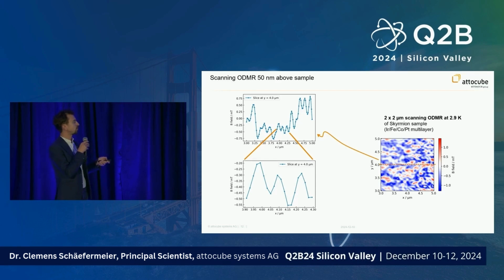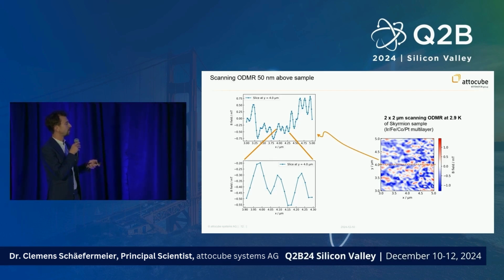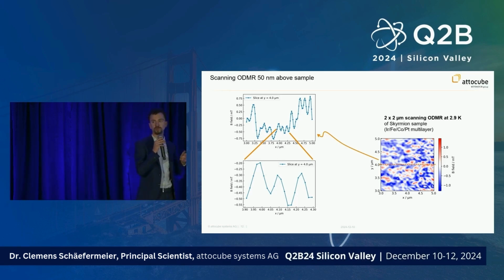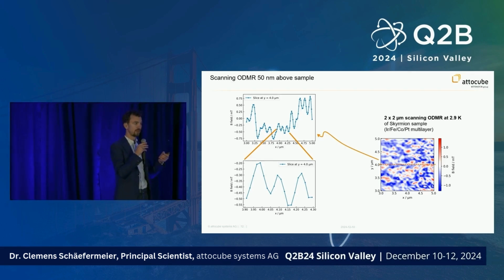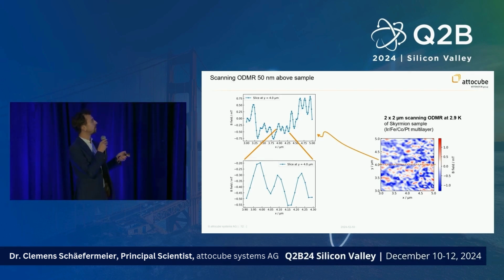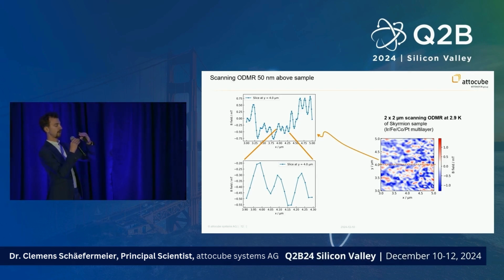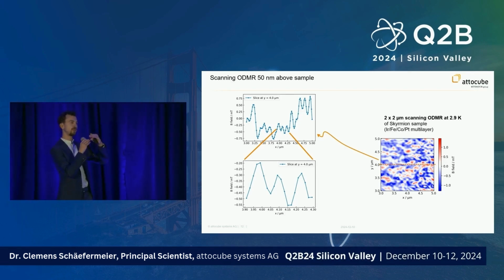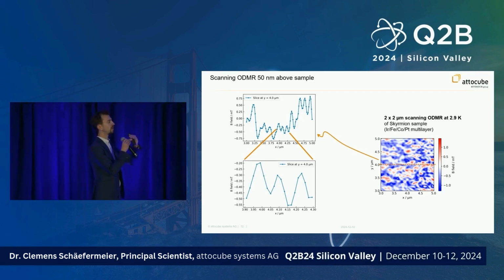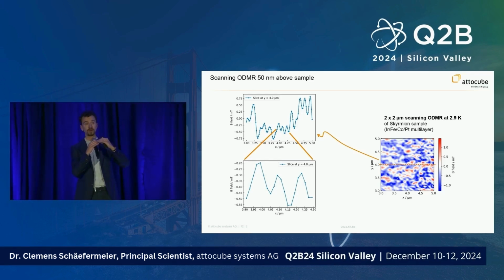So the cross section here shows that from a small to a larger magnetic field, this is around about 60 nanometers, and that matches pretty accurately what we expect here to be able to achieve in terms of magnetic field resolution, because this was measured 50 nanometer above the sample. So the diamond tip was not in contact, but it was 50 nanometer above the sample. And to a very good approximation, the distance tells you the magnetic field resolution that you can theoretically achieve.